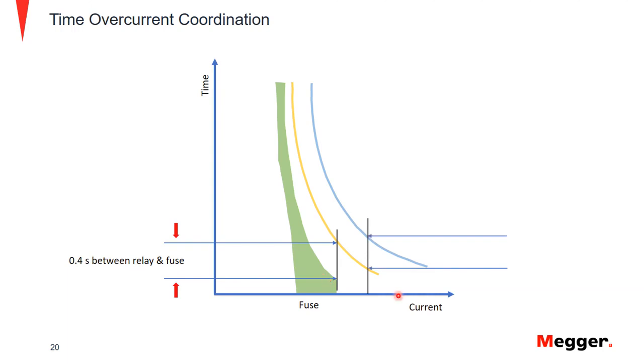So then also what we do need to look at is the coordination between the two relays. Not only the fuse, we don't want to stop here, but we also want to make sure that we're actually coordinating between the main feeder and our regular feeders. And usually we want to shorten that time just a little bit because they do operate faster than having anything melt down, kind of like a fuse would, since that's a one-shot go around there.